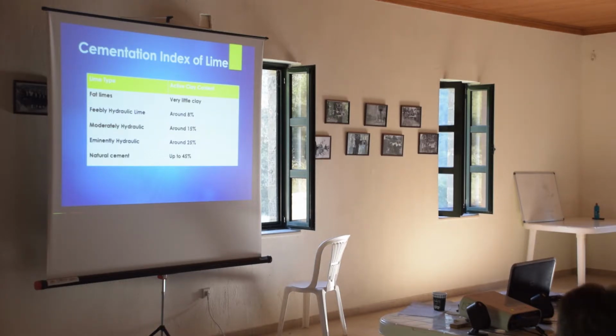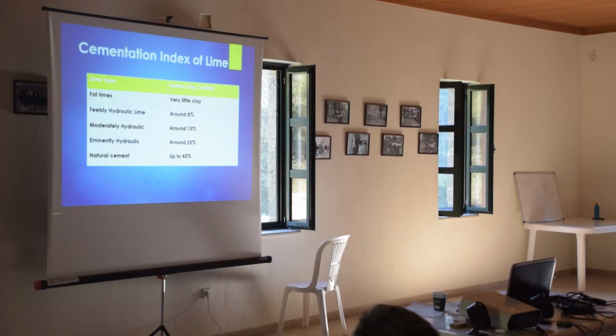Why would the water go behind the brick? Because we felt that there was a danger that because it was setting so quickly, any water within it was being absorbed into the bricks. And we were afraid that eventually you would get small fissures, small fractures. And if water got into that and got behind, there was going to be a problem.